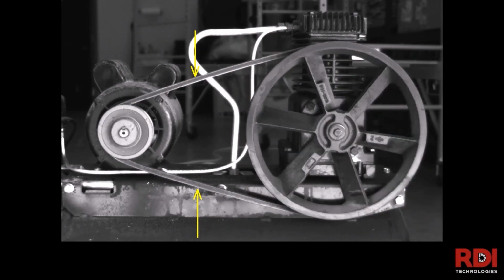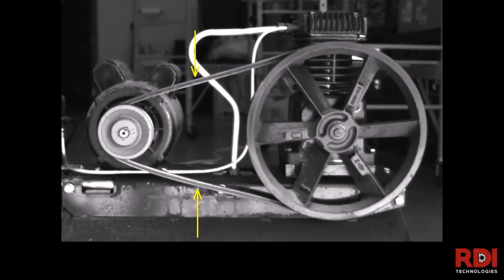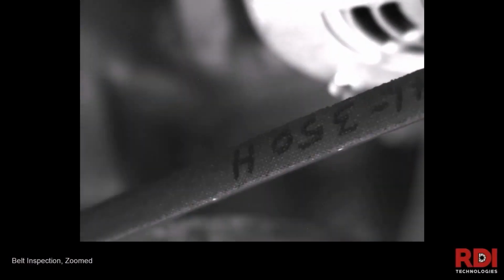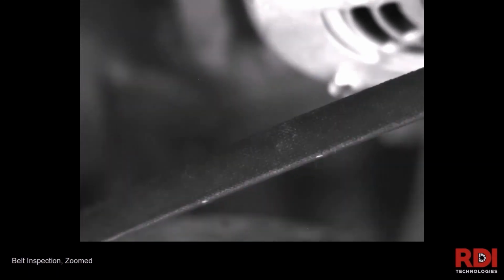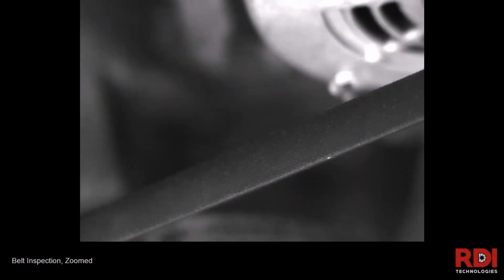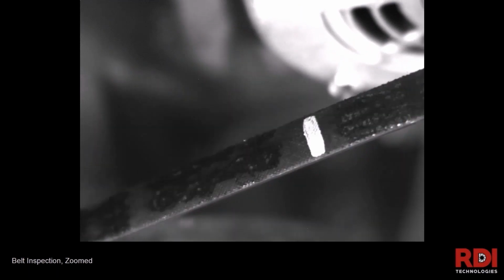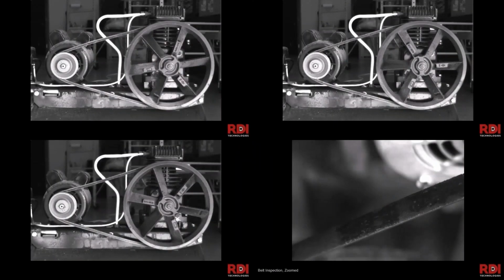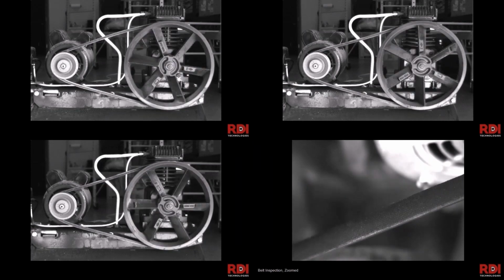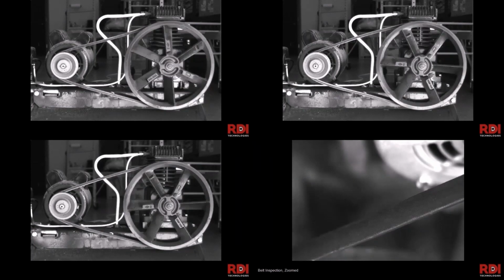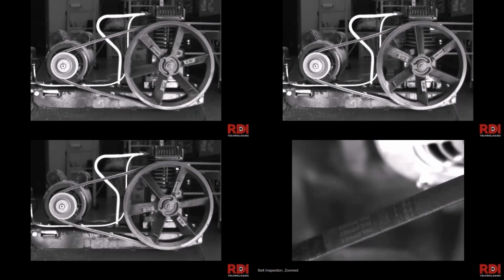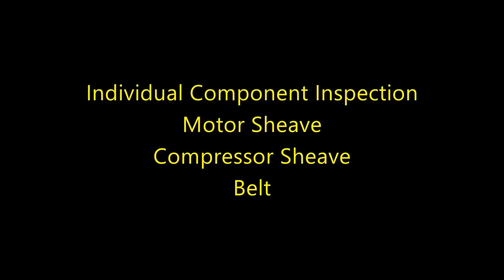You can also do a displacement measurement on the shaft. So you can actually measure the operational run out of the shaft in addition to just this inspection. You can quantify the motion of a shaft when you're measuring it, right? So here are all of them together. You have your own little video editor that allows you to produce these quadrant videos. We'll talk about that in a little bit.